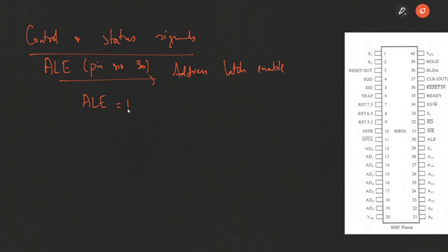These buses are used for dual purposes. They are used to carry the address as well as the data lines. So we need to make sure they work in a multiplex mode, in a time sharing mode. We need to make sure that these lines are used either for carrying the address or data. ALE will make sure that in the T1 state, these lines are used to fetch the address, so that the least significant bits of the address can be obtained.